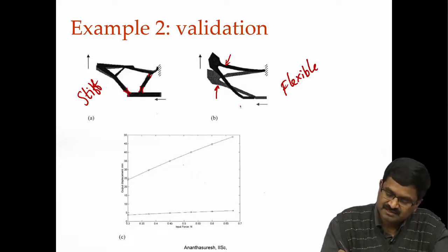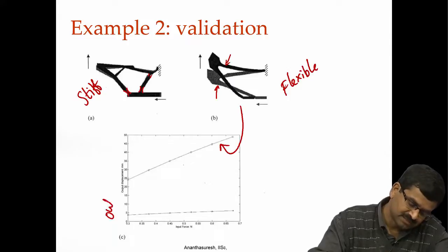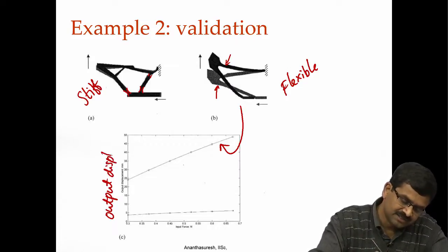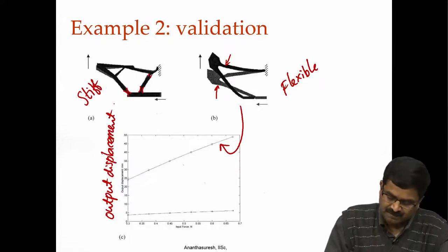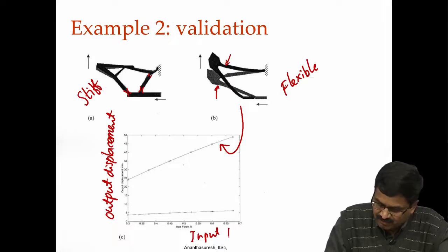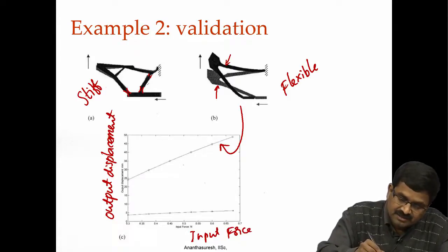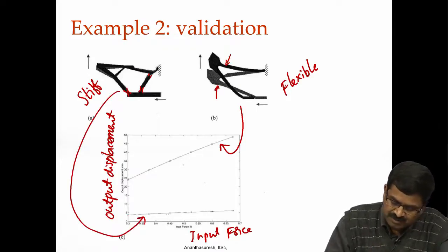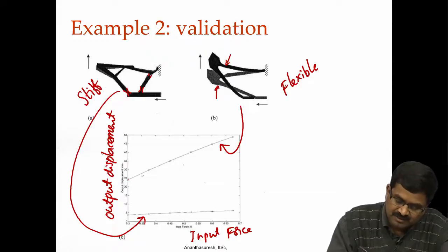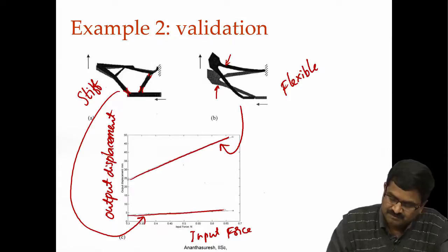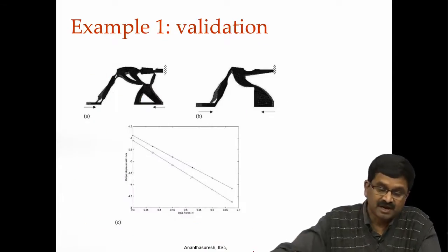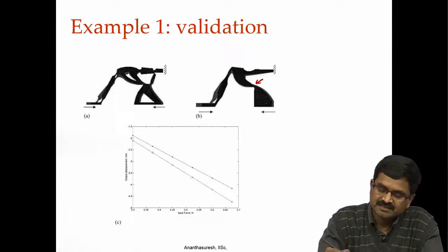What you see here, this curve, is output displacement, everything is the same. The two simple examples use similar data, and we got two designs using the usual MSE over SE, with and without this relative rotation thing, input force here. So, you see this one, this curve, small displacement, it is linear, this shows a little bit of non-linearity, but anyway that is not the point here. You get a lot more displacement for this mechanism as opposed to this. Okay. To prove to you, I even have prototypes that are made using this, and this is true for the other example where there were actually hinges occurring in the distributed thing also.